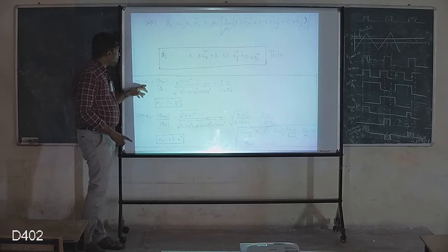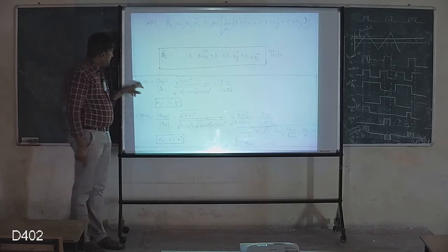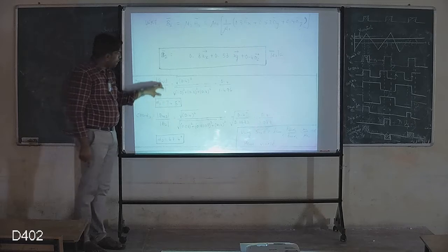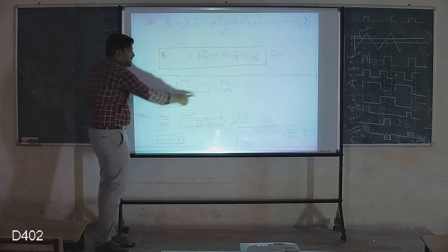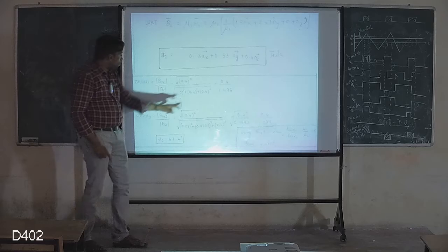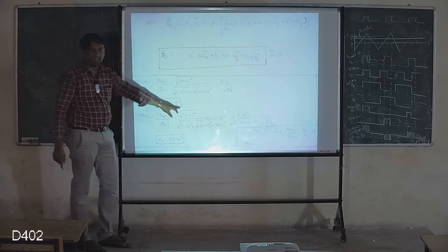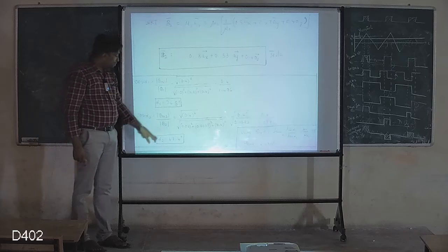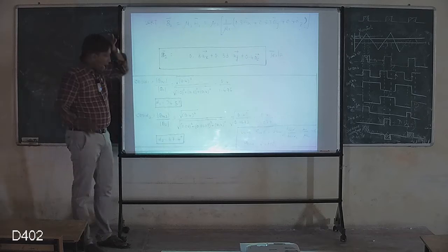Next, we have to find alpha 1 and alpha 2. From the figure, I can write cos alpha 1 is equal to Bn1 by B1. Bn1 is known, with modulus it is 0.4 squared, and B1 has three components, so squared. If I do that, I will get some amount. If I take cos inverse of this amount, I will get 74.5 degrees. Similarly, cos alpha 2 is Bn2 by B2, and alpha 2 is equal to 67.4. So alpha 1 and alpha 2 are obtained.